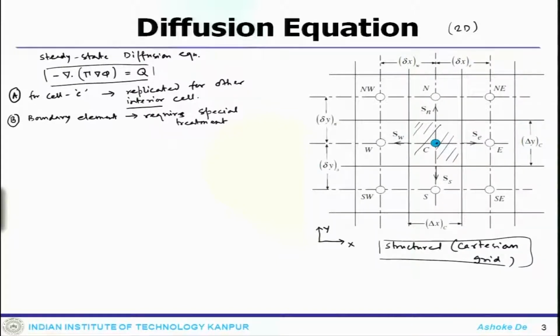That means the elements which are associated with the boundary, that actually provides the boundary condition at a particular plane or surface depending on the geometry which is 2D or 3D. If it is 2D, then it would be a face, if it is 3D, it could be a plane. So, that is the first task, that the physical domain is separated in two segments, one is interior cells, another is boundary cells. Once we do that, we just look at this picture.